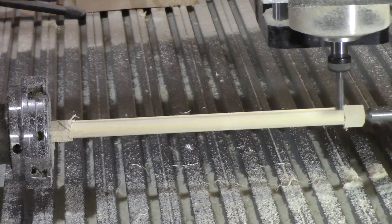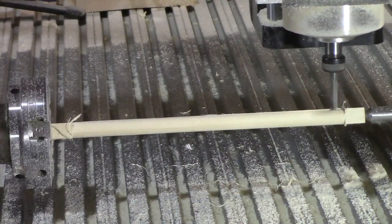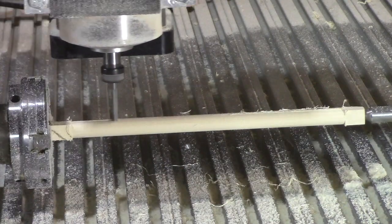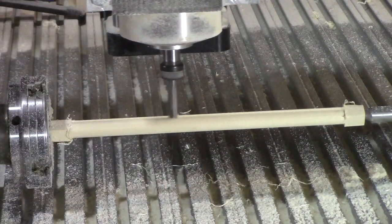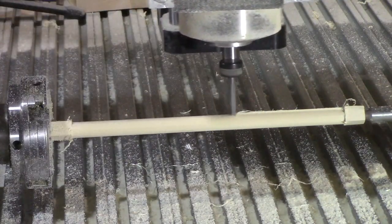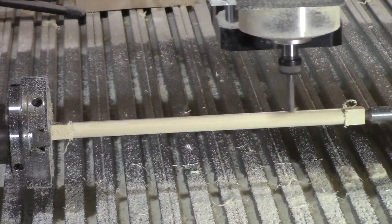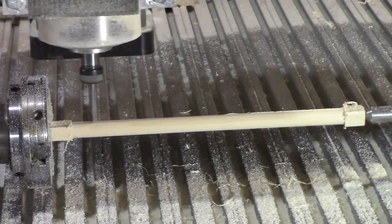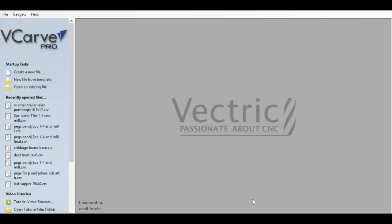And this is the raster cut versus the rounding cut. The rounding cut, as you saw in the last video, takes a lot longer than this one does. This one sped up about 8 times what it normally takes. But if you notice the feed where it's cutting across, it's pretty nice that way. And the rotary axis just steps 0.1 each time.